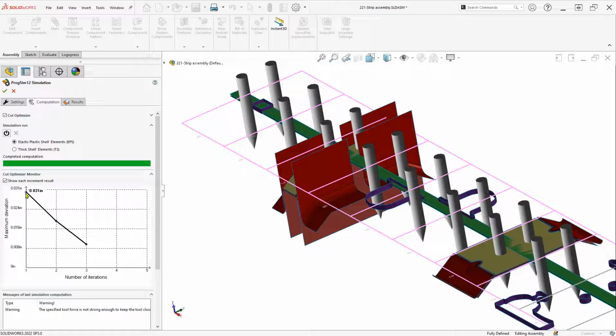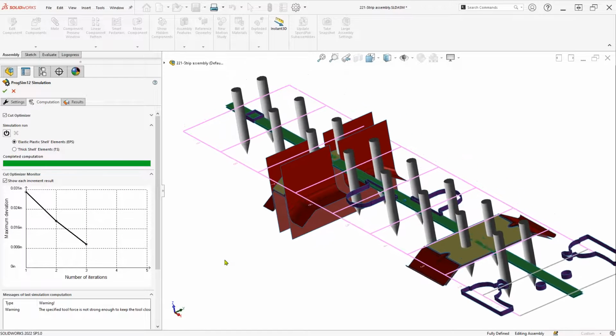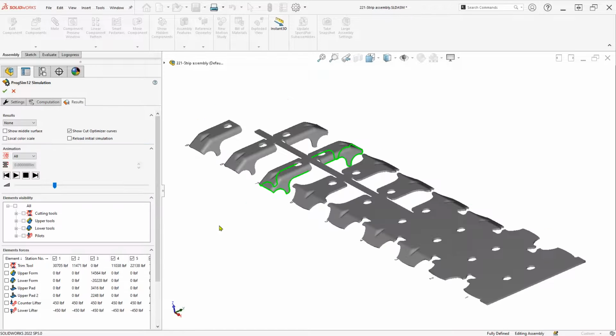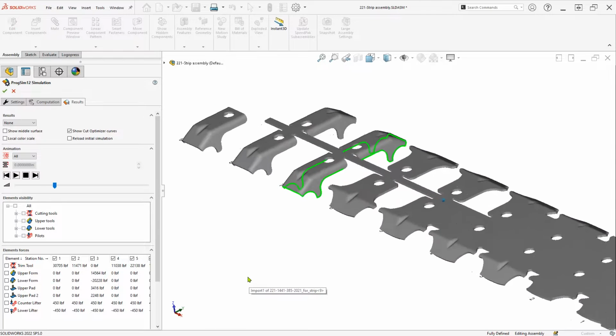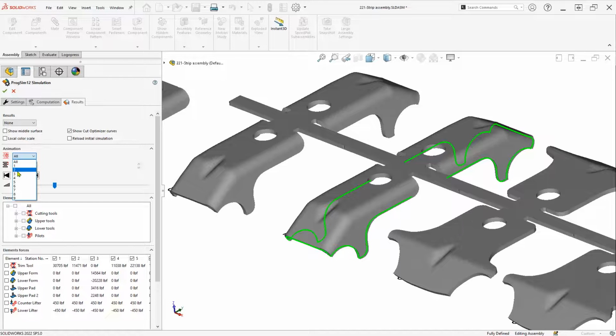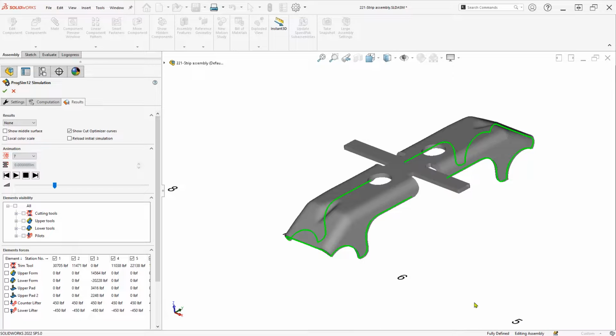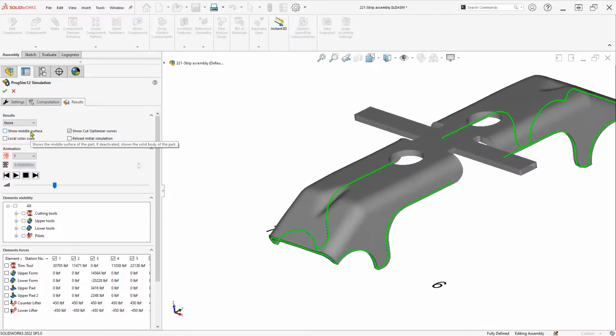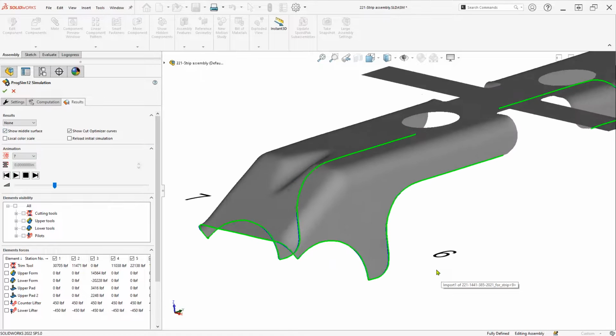Yeah. Okay. So you've got the little maximum deviation chart here showing that we went from 31 thousandths to 19 thousandths, down to probably about 9 or 10 thousandths here. We got within our target, and so it stopped at the third iteration rather than running a fourth and a fifth. You could accept these results and then come back and run an even tighter tolerance if you wanted, or you could say this is good here.